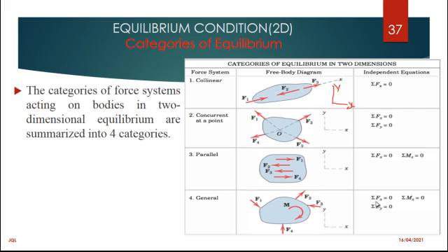So you can start with summation of forces in the x, then you're going to find your components. They are all in the y-axis. That will simply mean your summation of forces in the x is not applicable. You do the same for summation of moments, you say it's not applicable. Like in the case of forces which are collinear.